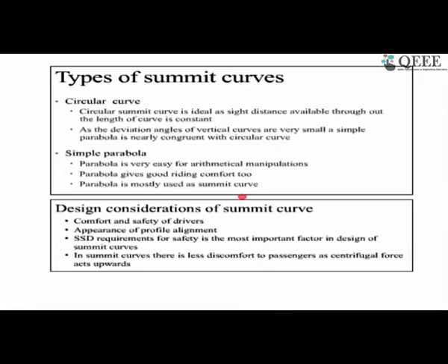Now, if you look into the parabola property, it is actually doing that. At the tip of the parabola you have the minimum radius, or the curvature is quite high. Whereas if you go far up, the radius increases, it's almost going to tangent and going to infinity and meets the tangent nicely. So this is why it is going to give a good ride comfort.